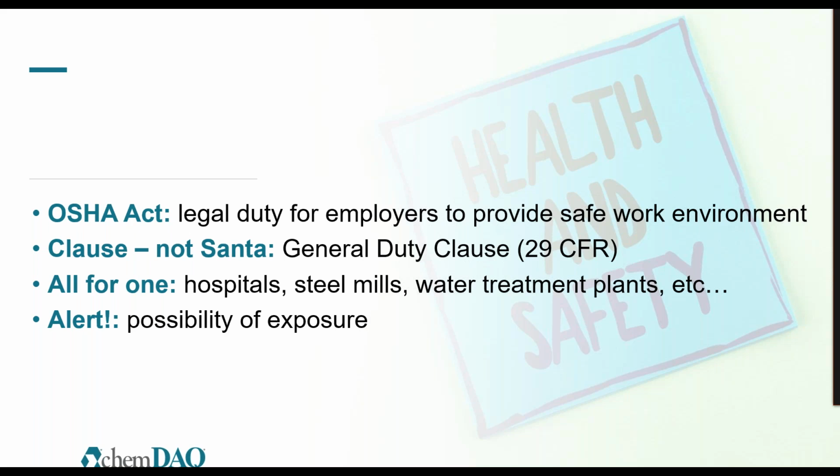Yeah, hi Matt. I'd just like to jump in if I can. Yes, please. The IDLH is the limit where after 30 minutes of exposure, it either causes some permanent damage, or else the person will be inhibited such that they can't get out of a location. So if you get something like hydrogen peroxide, which is a severe irritant, even though at the IDLH they may not suffer serious damage, they will have so much irritation that they would be unable to find their way out.